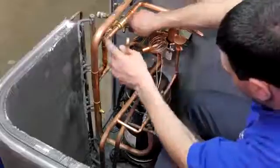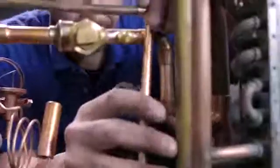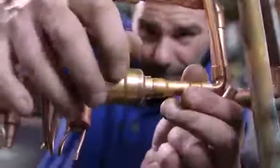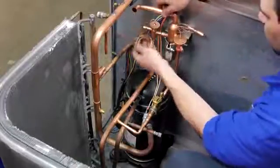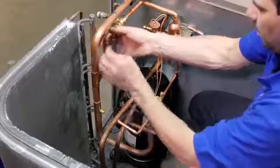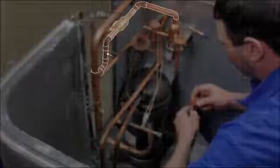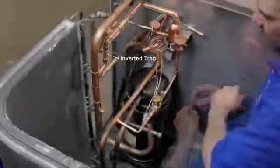Connect the liquid line T to the liquid injection valve of the APR control, opposite the hot gas valve connection. This is labeled L on your installation diagram. Connect the mixed gas discharge line from the top of the desuperheating chamber of the APR control to the T in the suction line. This is labeled M on your installation diagram. Due to unit configuration, we had to pipe into the vertical suction line and create an inverted trap to avoid oil migration.